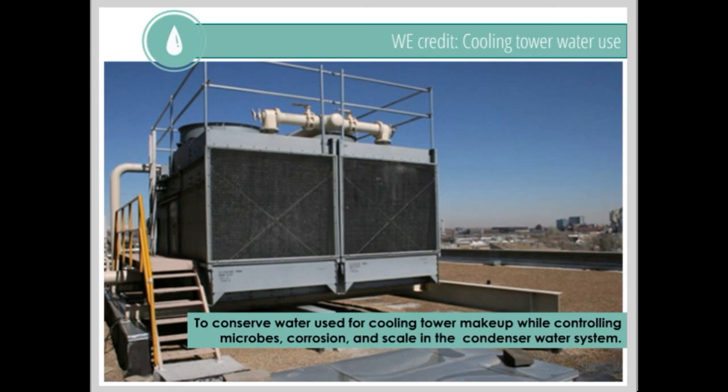To significantly reduce makeup water inputs, it is important to achieve target cycles of concentration. Cooling tower or evaporative condenser water efficiency is measured in the number of recirculation cycles before water must be removed by blowdown. Increasing the number of cycles can save thousands of gallons of potable water during a building's peak cooling periods. Chemically analyzing makeup water allows for calculation of optimal cycles.